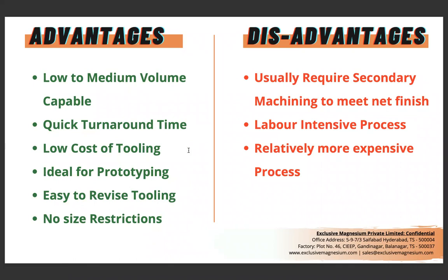Even when you're prototyping and you want to revise the design itself, sand casting makes a lot of sense because you can very easily revise the design and try it again, do another batch. So that's a good advantage for early stage companies and early stage products. There's also no size restriction in that sense. We've done castings which are as small as 250 grams, and the highest we've done is 2.5 tons. So in terms of size, sand casting can accommodate fairly huge sizes as well. That's a major advantage.